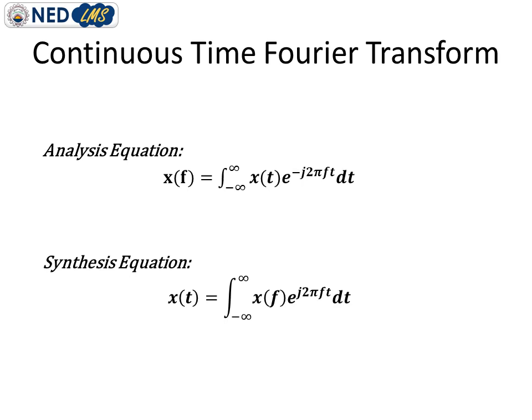Talking about the CTFT technique, the analysis equation is written on the slide, and as you know, it is a continuous time signal as well as aperiodic. So in the analysis equation we have used the integration sign, which represents continuous time, and it is aperiodic, which is represented by the limit of the integral sign, minus infinity to infinity. Rather than one time period, we are using the values minus infinity to infinity as the limit of the integral.